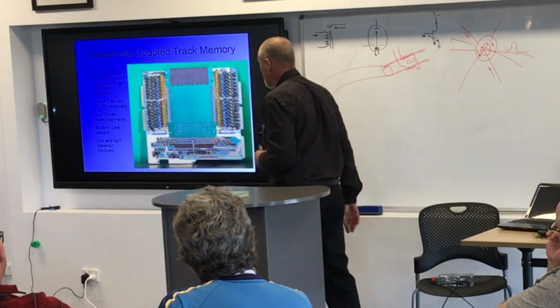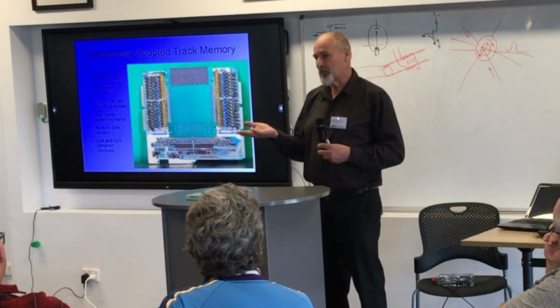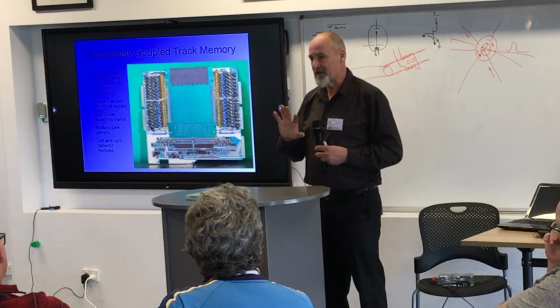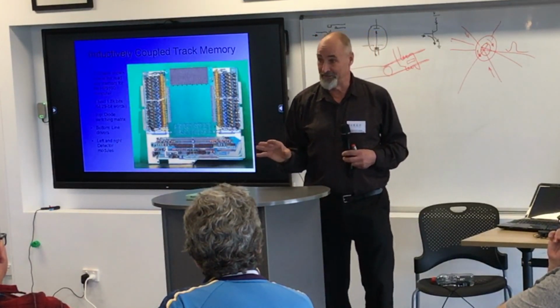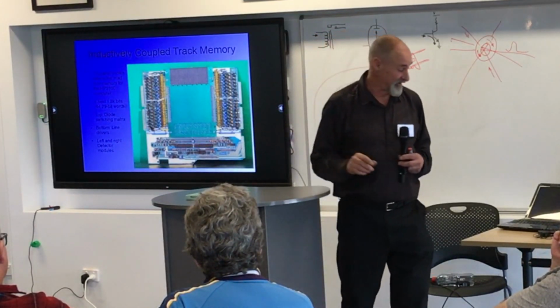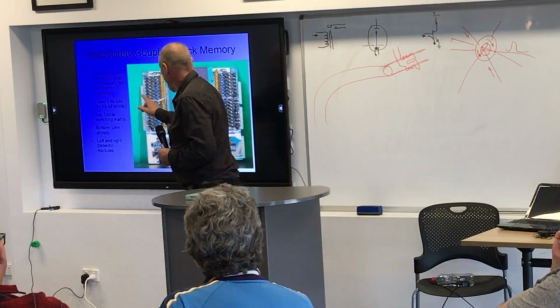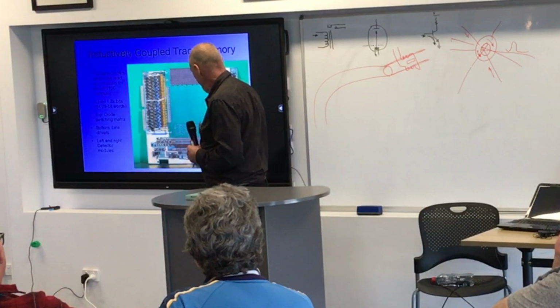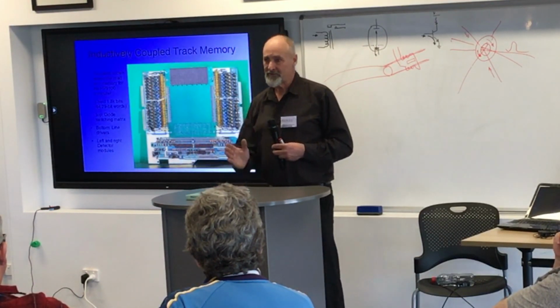Behind that panel are 8 Teflon double-sided circuit boards with tracks and vias, nothing else. So how do you store data with tracks and vias and no other electronics aside from differential amplifiers to detect, a diode array to switch, and pulse generators to send a pulse through the address lines?